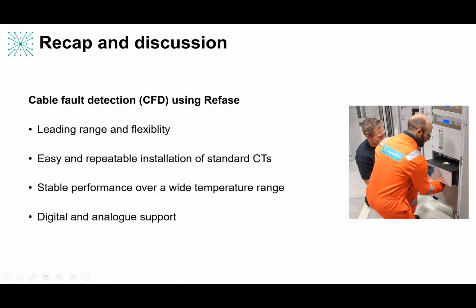One other angle here, Philip and Stephen, would be where you've got fiber either co-located or not co-located with the phase conductors, which would enable an OTDR fault location to be quite specific. Is that worth explaining? Yeah, that's a very good point. If the optical fiber, as it is in a lot of subsea cable systems, is co-located with the conductor, as in it's in the same cable embedded, or it's very close, then a fault, which in a multi-phase cable will often be eventually catastrophic, will cause damage to the fiber at that point.